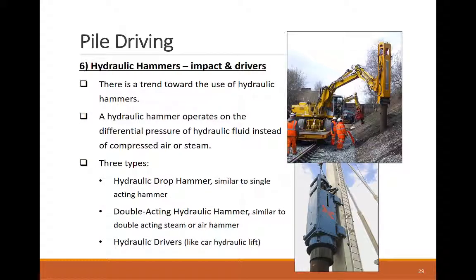Hydraulic hammers utilize hydraulic pressure fluid instead of air and steam to drive the piles. Similar to compressed air hammers, they can be single and double acting hydraulic hammers. There is also a hydraulic driver that's similar to car lifts. Hydraulic hammers and drivers are becoming popular as you can utilize the hydraulic system in most heavy equipment like excavators and cranes to power the hammer or driver.